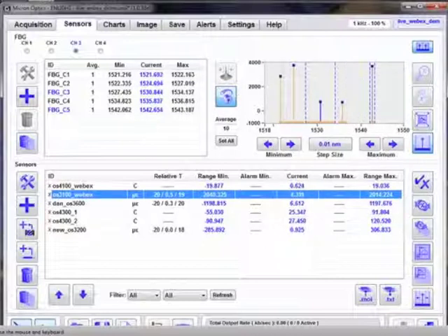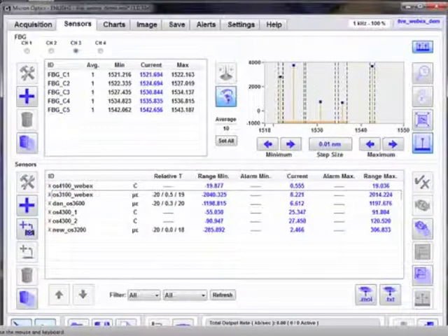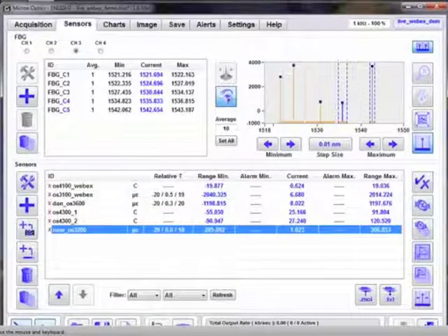And so now, notice we have an offset here in this OS3200. That could be due to an offset in strain. Well, it would be due to an offset in strain, and any sort of an offset in temperature would have been tracked by its compensation expression. And now if we want to zero our OS3200, we can do that independently without affecting the value of the OS3100, which is presently around 567.